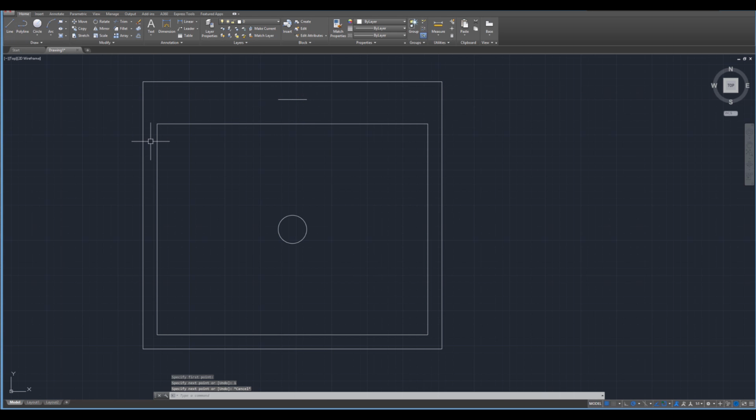After you've done that, use the line tool one more time to draw the front of the sink. And this is going to be out roughly 3 inches, so we're going to type in 3, enter. And then moving out in this direction, it's going to be half a unit, so 0.5, enter. And then using the line tool again, we're going to go out the opposite direction, an additional 0.5 units like that. Now we can use the line tool to connect this with this, as well as this end with that end. So it's going to look something like that.